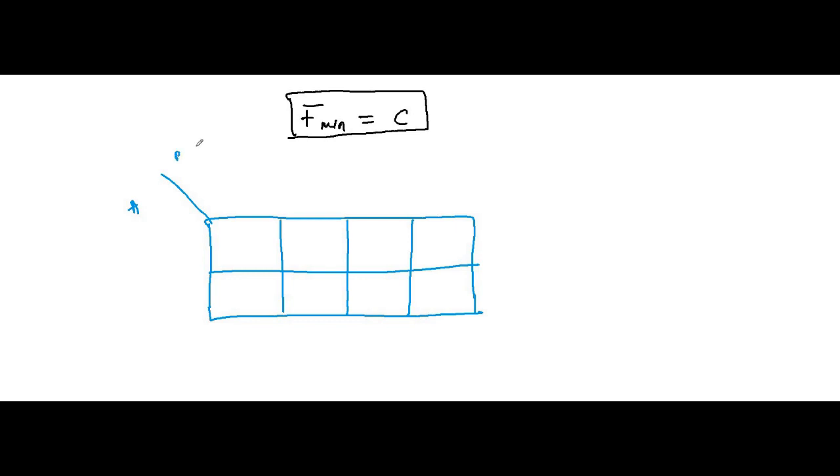A, B, C, okay, 0 and 1, here it is 0, 0, 0, 1, 1, 1, 1, 0. Here it will be A bar, here it will be A, here will be B bar C bar, B bar C, B C, B C bar, and each of these cells represents a particular min term, which is 0, 1, 3, 2, 4, 5, 7, 6.